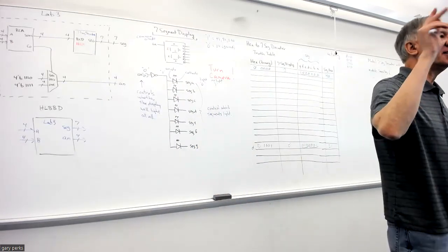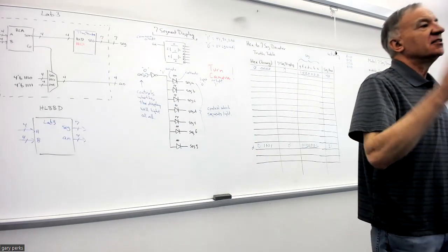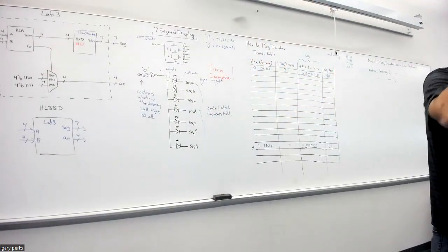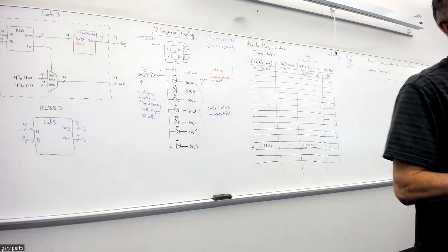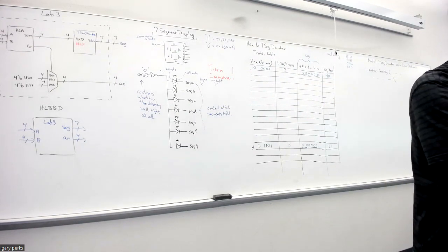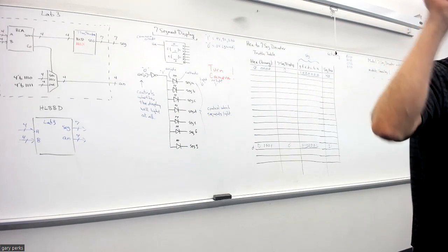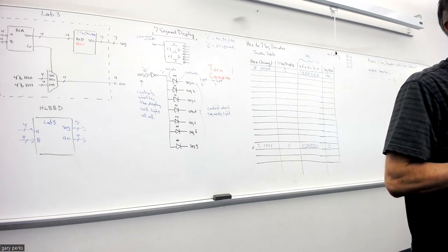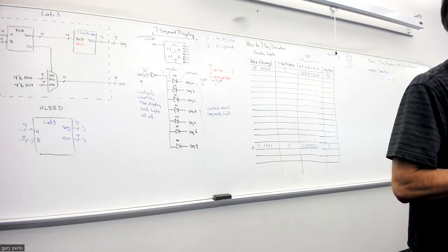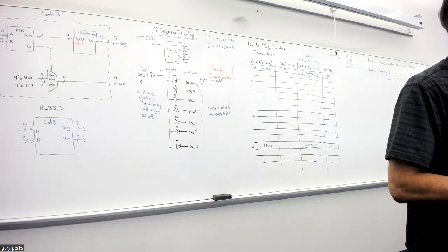But this is where instead we're going to use the power of the software of Verilog. Last class, for the MUX, you saw how to use an if statement. What did that if statement have to go within? An always_comb. What does the comb, C-O-M-B, stand for? Combinational. What do we mean by combinational? Combinational logic doesn't have memory. Right, exactly. And if you don't have memory, you also don't have this thing called a clock.